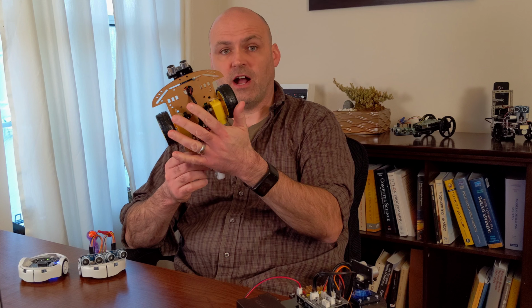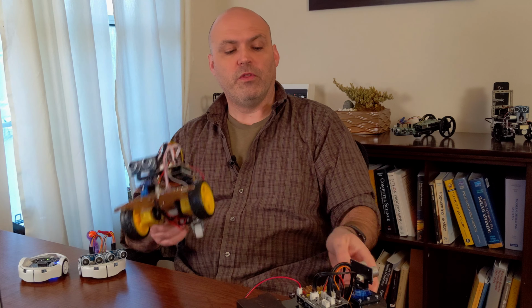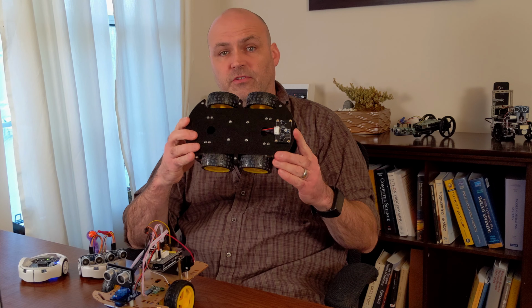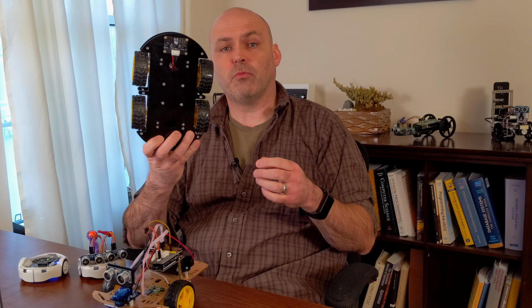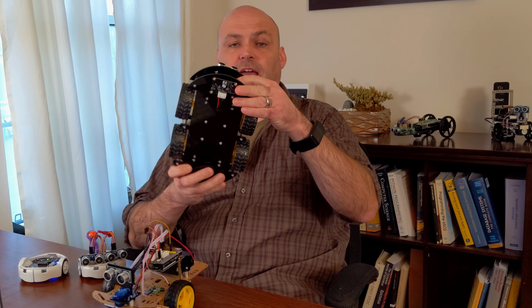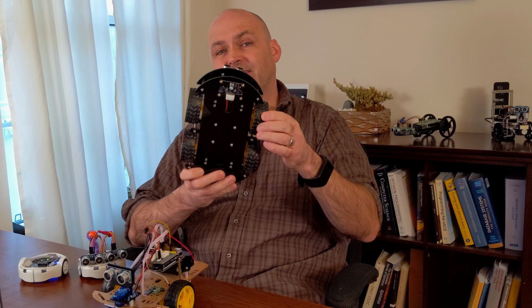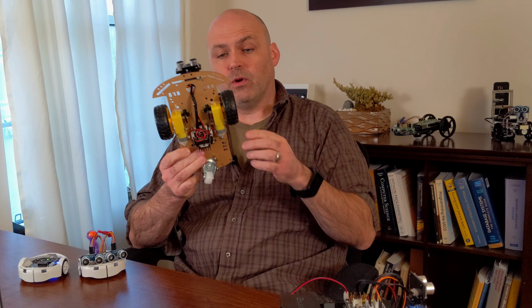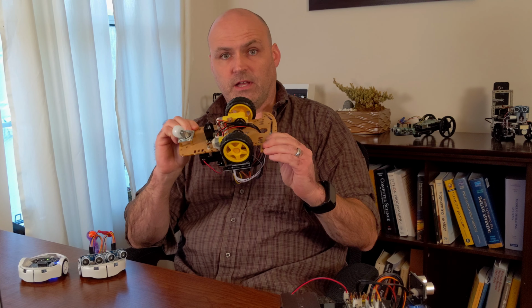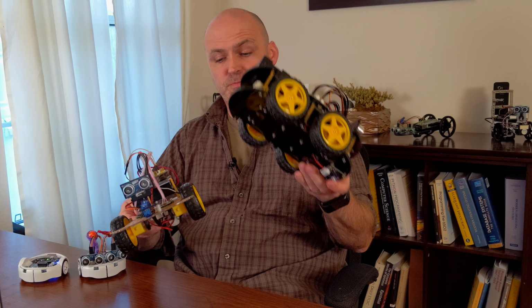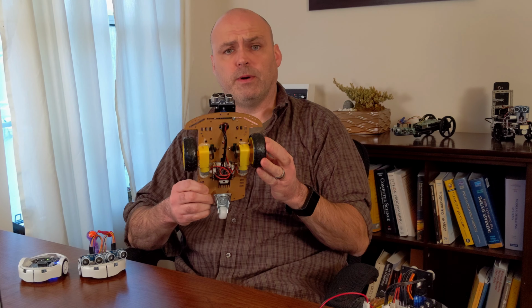It's differential drive with just two wheels. With this one, there's always the risk, and I would say it's a pretty significant risk, that you're going to introduce more error as it turns because you have four wheels and it's not going to pivot as cleanly on a single contact patch on each side as this one will. For that reason, I like this chassis a little bit better, although this one is of much better quality. But you can use any kind of robot like this.